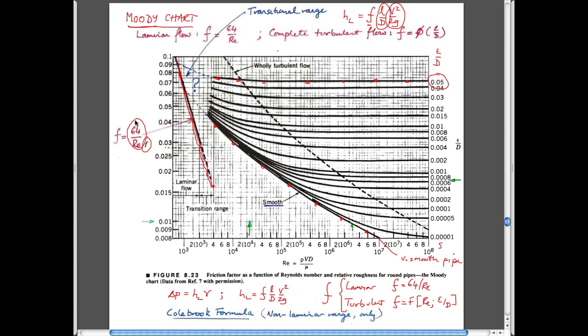Nothing more than that. And so the other notable point in this is that for these behaviors here, it's not possible to get a simple analytical solution to figure out what this friction factor is. The only way we get it is by doing experiments. And if we did that now, even with all the computer power we have, we'd have to reproduce this graph, we'd have to do exactly the same thing, just by experiment.